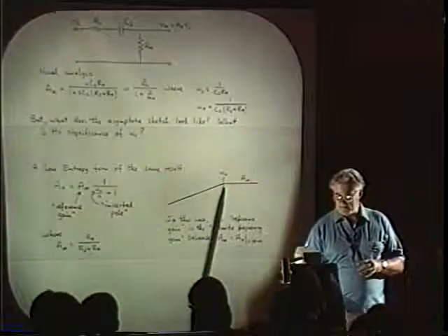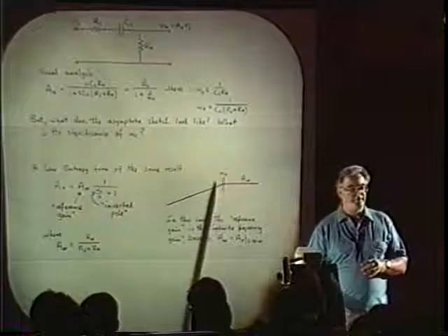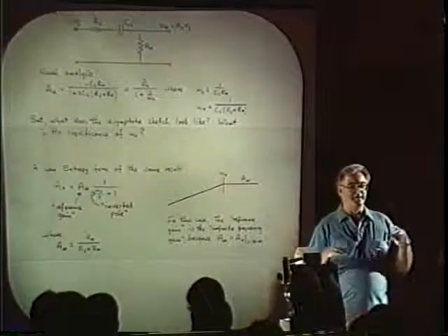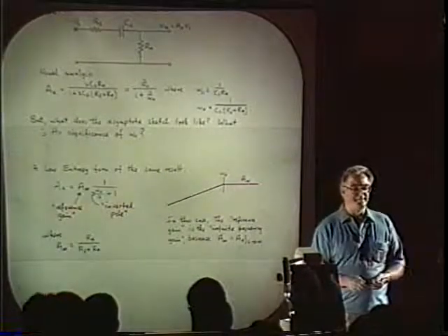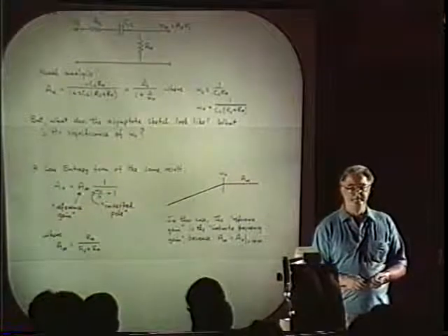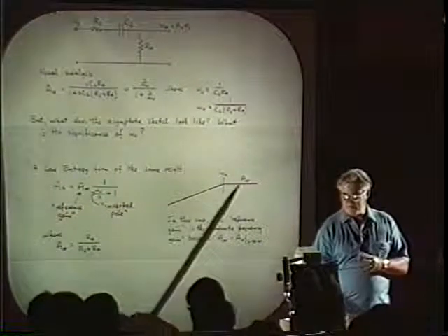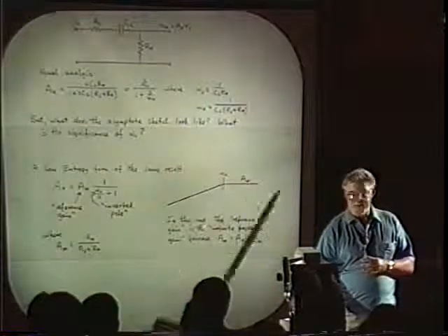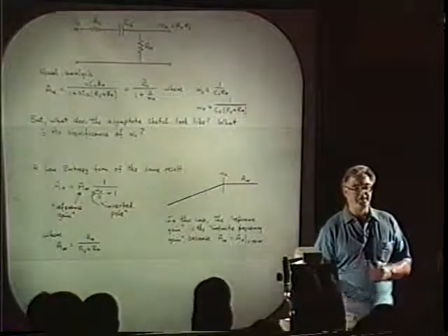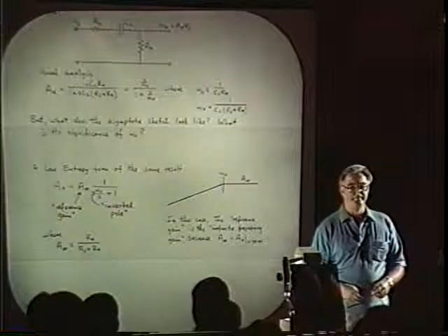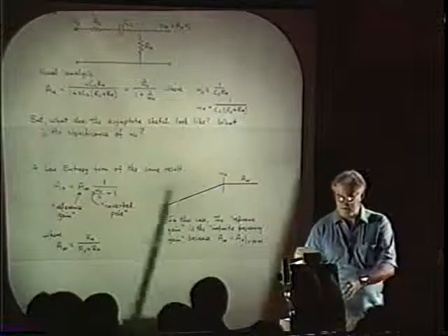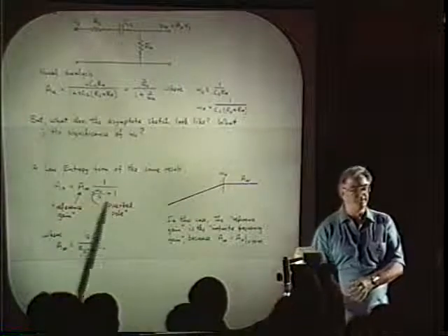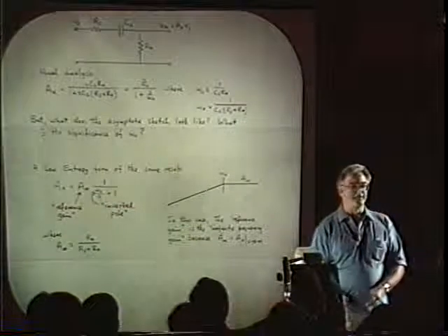Low frequency poles, inverted poles, come about because of coupling, bypass, and decoupling capacitances. The significant feature is the reference gain, which is the coefficient in front, is the high frequency end of it instead of the low frequency end of it. And all that inverted poles do is expose that symmetry.